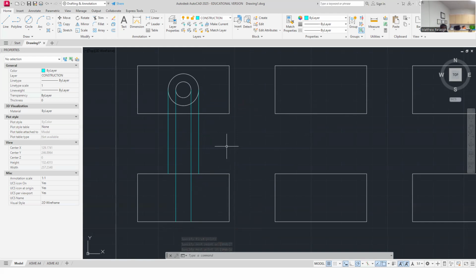So counterbore, if it was cut out of a plate or whatever, they may put an initial hole in the plate where it goes. Sometimes machinists don't even like that. They would just like to maybe be delivered this square block cut. And then they would maybe go in and actually do the counterboring. They would find the geometric center of their part, and they would have essentially a machine, which is like a drill or a drill press, but it's a mill is what you call it in a machining world. And it will bore that hole with the right tooling to the right size. And then we'll come in and put a whole different tool in to actually do this bigger diameter cut. And that's going to fit a bolt, is what it is.